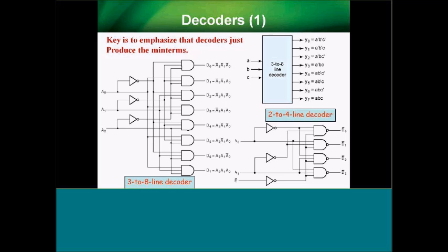Okay, so like we have down here, the bottom right one is a 2x4 line decoder. This one is a little bit different: it's going to kick out a 0 on the line that you select. That's something to show them, that it doesn't always have to be positive logic. Of course, it's got an inverted enable also. I tell them that's an interesting thing as well. Not only is it the enabling concept, which is important, but frequently the enable is inverted because that saves power. Most of the time, you'd rather have the line be kept at ground or low than kept at 1 all the time and have to take 5 volts. Okay, so that's one thing.